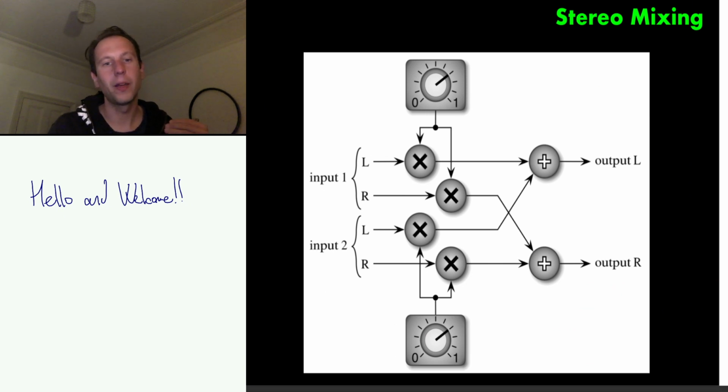The reason is that you cannot process both left and right signal through a single gain stage. In other words, by using a single multiplier, because that would mean that you have mixed the channels together. If you send both channels into a single multiplier, there is no way of separating them out again.